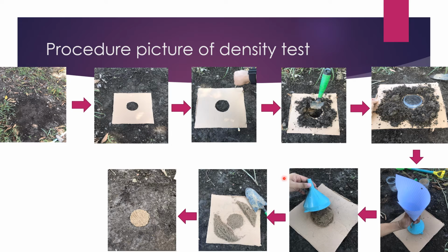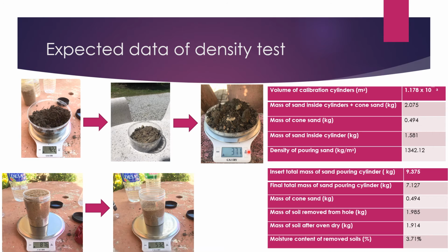The moisture content of the excavated soil is determined by taking a sample of soil from it in a moisture content dish, weighing it wet, drying it under the sun for 6 hours, and reweighing.